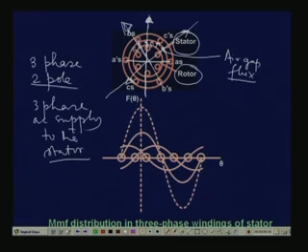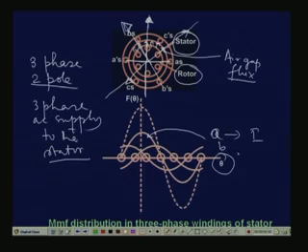For example, this is a case where the A phase contains, let us say, the full current I. This is a snapshot of the MMF distribution across the motor, plotted across mechanical angle. Similarly, the B and C phases provide the return path of the current, so it is minus I by 2 and minus I by 2.